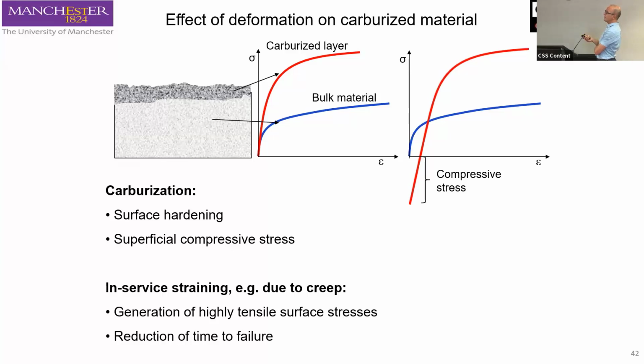But the problem is, when you stress the material and you have a deformation greater than 0.1%, you are now developing very high levels of tensile stresses in the material, which are responsible for the development of cracks that we have seen from in-situ testing and digital image correlation.